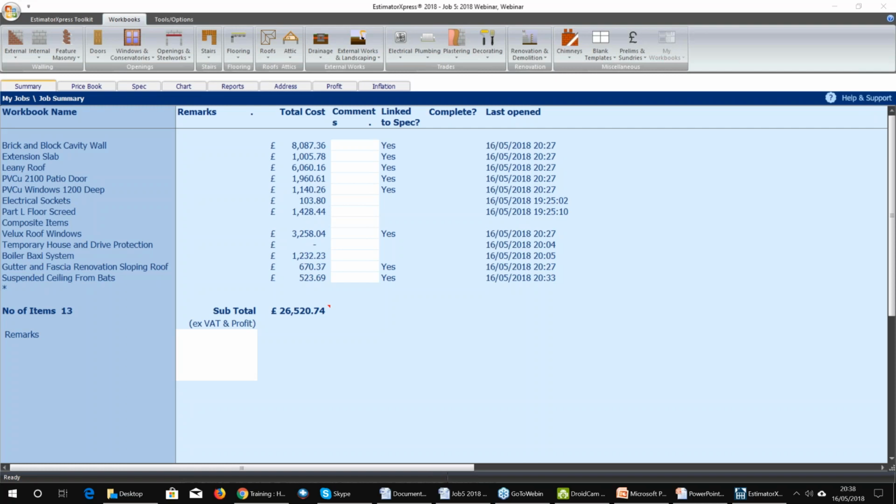Oh, actually got a question come in. Yeah, I have just given myself a rod for my back. Key thing there: take some pictures. And also, if you've got access to it, no matter what kind of access you've got, never try and price a roof from standing on the ground. Many times that has gone horribly wrong when someone's priced one up, and it's not exactly as expected.